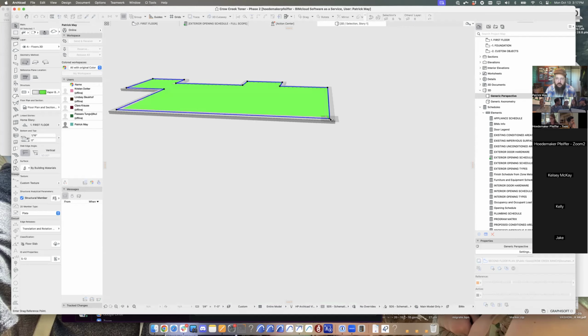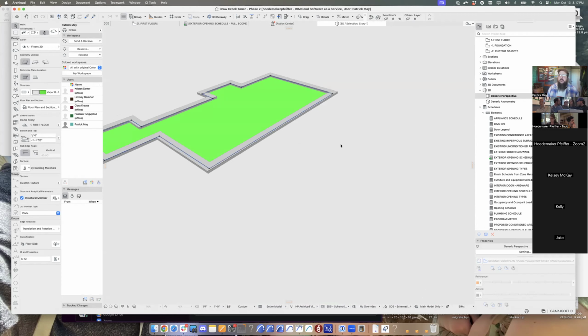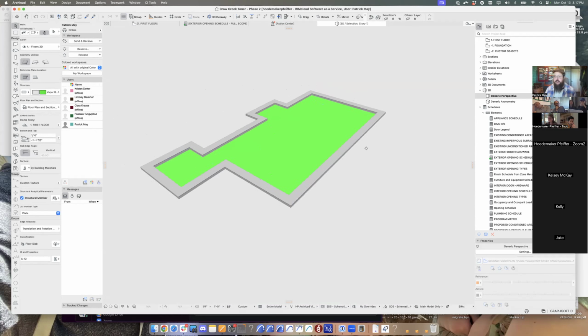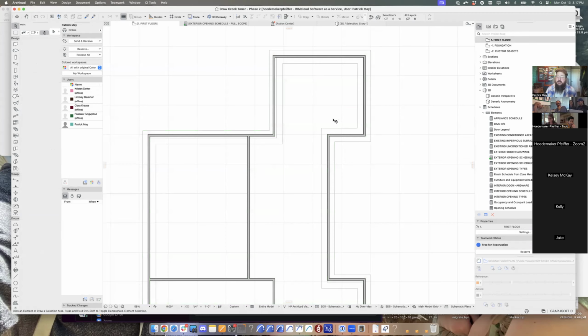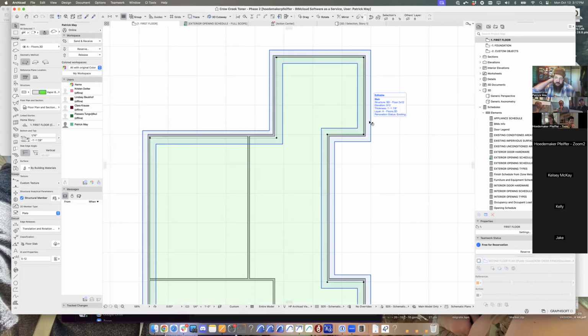You trim out your site mesh to the inside face of wall, not to the exterior face of wall? Usually, yeah, because I usually want the foundation, basement, stem walls to be trimmed to the site as well, so that when they move, they're trimming the site. I don't have to worry about being overly fussy about things. Again, that's another one of those where it's case by case, there's 100 different ways and combinations of ways to do it. But yeah, I would typically model this as a vapor barrier to the inside face of my foundation, and do a subtraction with upward extrusion.